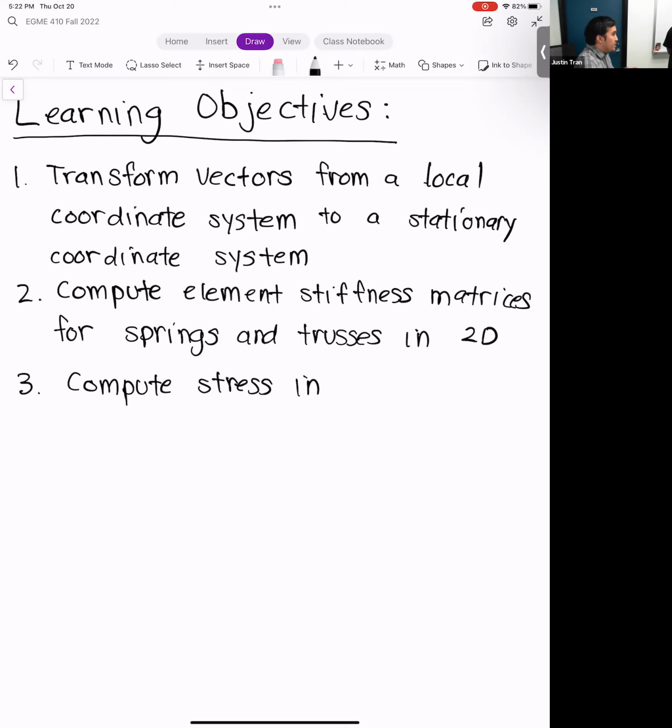So you can input that as a boundary condition in ANSYS. You can say we have a heat flux, or an energy input of so and such watts per meter squared. Then you can run the simulation and check to see if the temperatures exceed, you said 60 degrees? Yeah. That's how I would do it, or at least how I would start. You get a CAD model, put it into ANSYS, and input a heat flux. On the other side, you can probably put a convection boundary condition like ambient air temperature. Then you can see how that is.